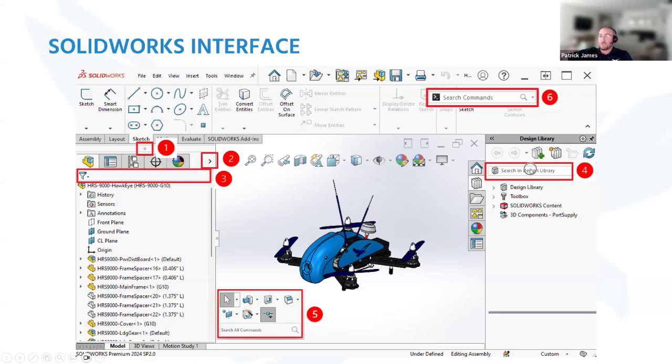If you don't know exactly where you're drilling down to, like the command search here, you can hit the S key on your keyboard. That brings up some common commands, and there's another one you can search for. Probably my favorite way to search commands, and by far my favorite search button, is up here, through search commands. I think by default forever this was help. It might still be help, but I've switched it to commands. You can hit the little drop down at the top and switch it to search commands. I use this one all the time. If there is a button and I don't know exactly where it is, I will always go ahead and grab that.